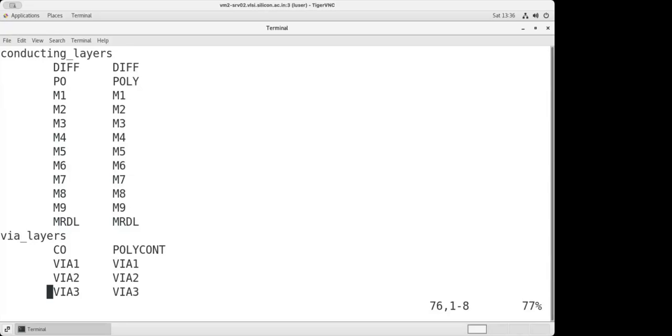And the foundry is saying, see, I don't care about these different naming conventions and everything. We have a concept of layer number. So when you are going to provide whatever you have designed to the foundry, you are not going to provide it just like that. There is something known as a database you will provide. That database is basically a GDS database. It has become a standard nowadays. It's a graphical design database, so that is known as a GDS database.